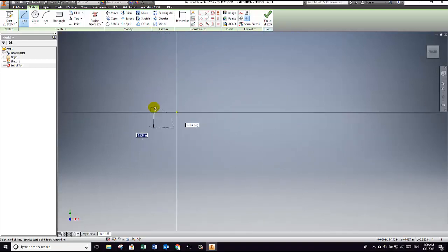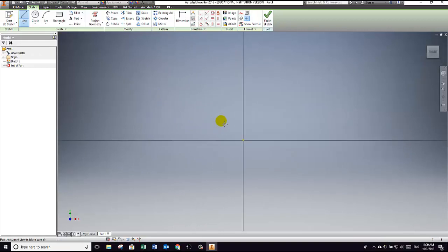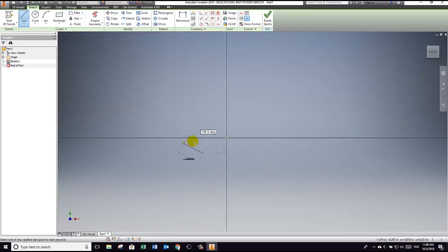I'm going to use the scroll wheel to zoom out. And if you click on the scroll wheel like it's a button, I can reposition where the center of my drawing would be. So 2.25, this program works in decimal. And I don't have to be exact, I can just be close. Okay, 2.25. And then we go over approximately 0.75 and then down 0.75, remembering what our shape looks like.